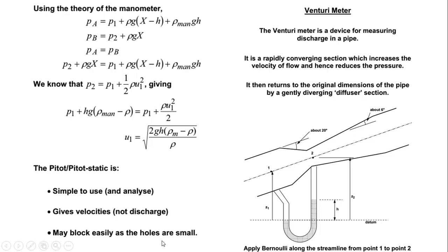For those who are doing aeronautical engineering, we work with a lot of pitot tubes for calculating velocities of an aircraft, etc. The other setback is that they can block easily, and when they block, they can cause harm to aircraft. There are some aircraft incidents and accidents that have happened due to blockage in pitot tubes. So it can be a setback and cause some distraction.